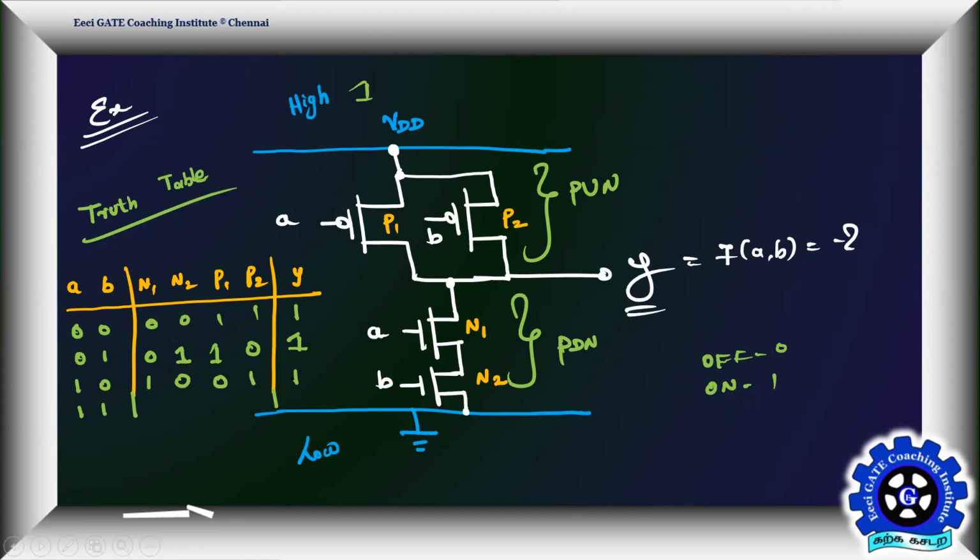Yes, sir. So the beauty of digital logic is, after the class, if you see only this slide, you won't understand, because a lot of understanding is happening in the slide itself. Based on that only, I'm writing every row of our combinations, correct? Yes, listen carefully and understand things. 1 and 1. Both NMOS transistors will turn on because they are looking for active high.